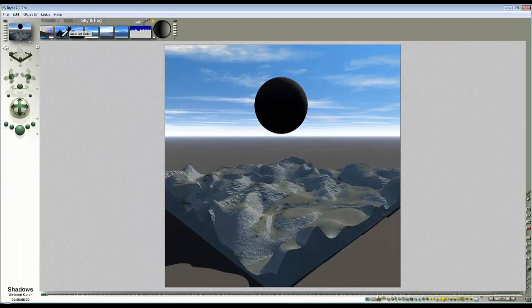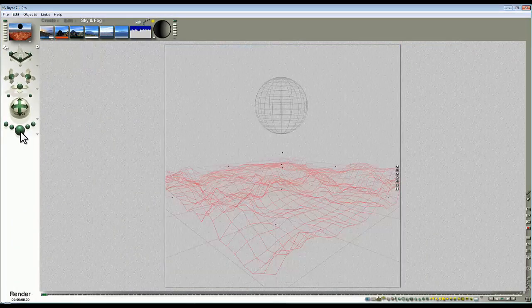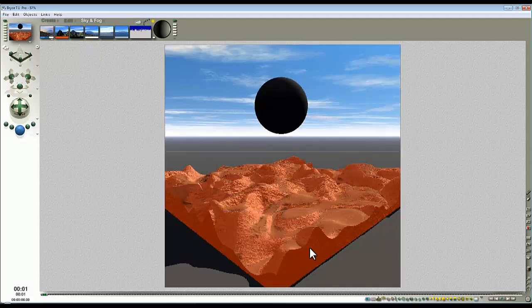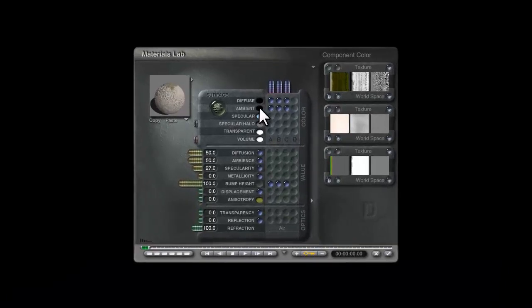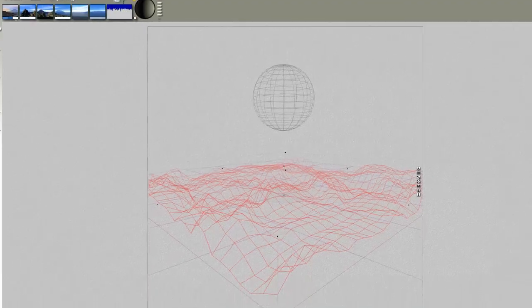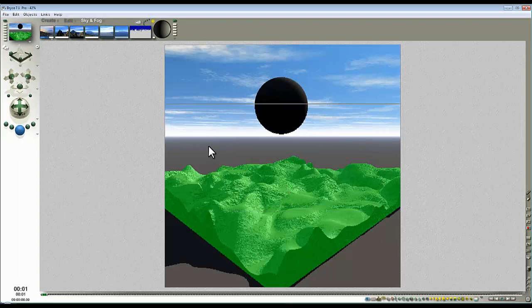So if I choose an ambient colour that's quite striking, that's the global ambient colour, you can see that this now looks bright red. So you can provide a colour shift through the ambient channel to whatever is provided globally here. If you provide full white, what you will get, if we go back in the material, is the output from this colour choice. So if we go in here and change that to green, for example, and come back, then you can see the material is now glowing green, although the global input is white.